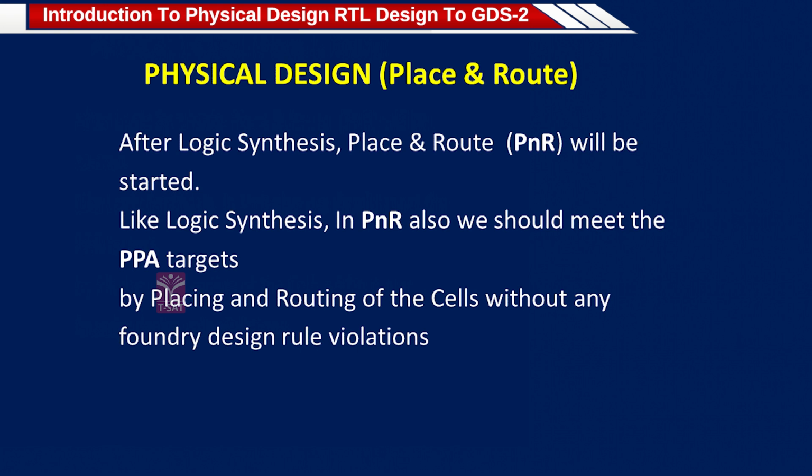If you complete the interconnections, meaning routing, then one more parameter called net delay comes into the picture as a part of physical design. We are doing timing analysis, STA, in logic synthesis. Similar timing analysis we need to do in place and route also. But the main impact is that we are introducing net delay.